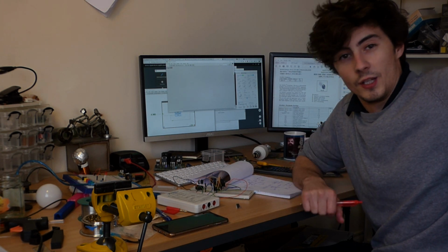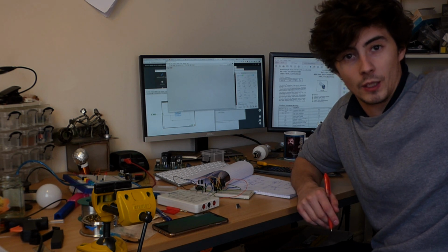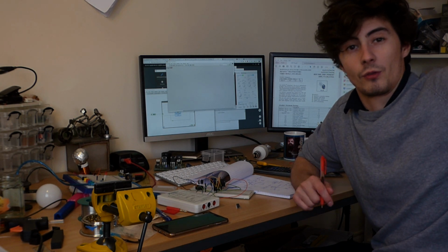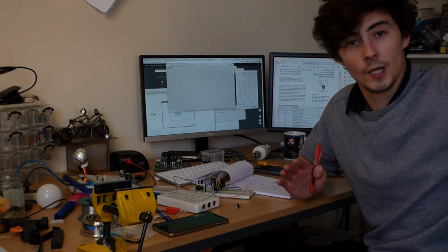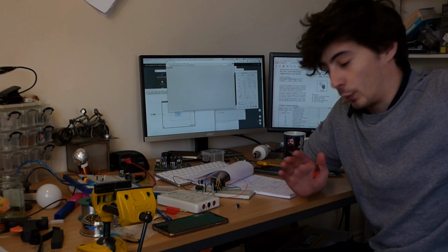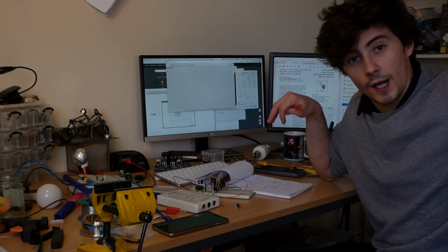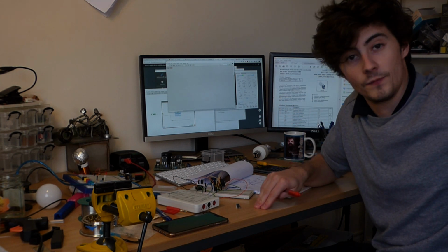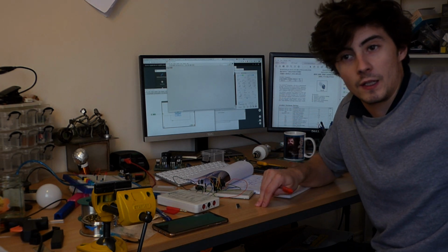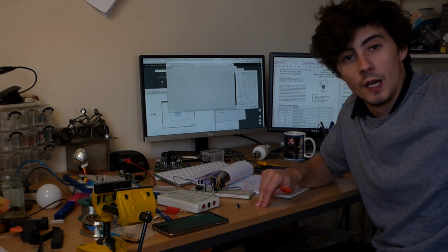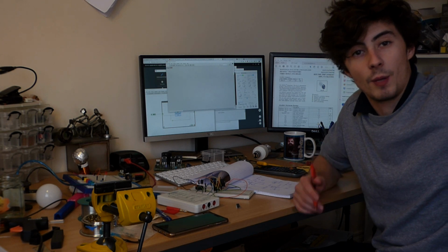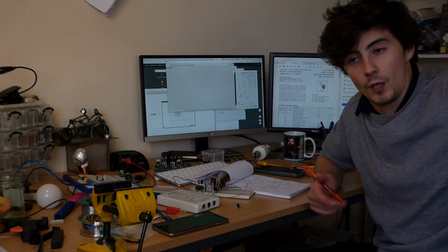So I'll use it in this just because I need something to drive it very quickly instead of using an actual microcontroller where I have to write actual C code, just to speed things up. But the main point of this is to run through a design exercise using the IR2110. Commonly these calculations are the bootstrap driver, the bootstrap capacitors that are needed, the bootstrap diode, how we can spec that out, make sure it won't fail, likewise with the capacitors.